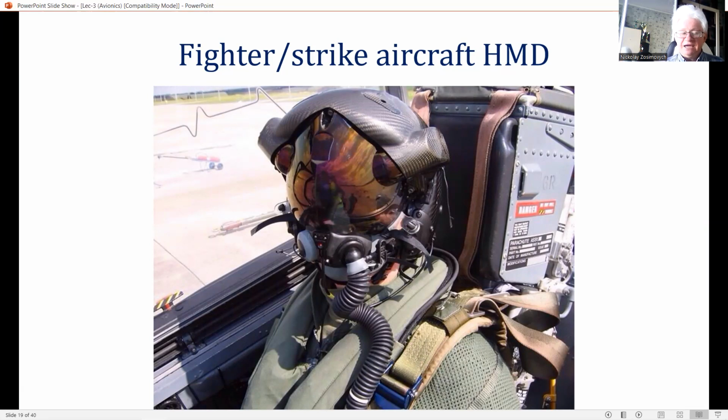This allows a standard spherically curved aircrew visor to be used to carry out the combiner and collimation function by the addition of a neutral density reflection coating. The visor coating provides high display brightness whilst maintaining high real-world transmission.